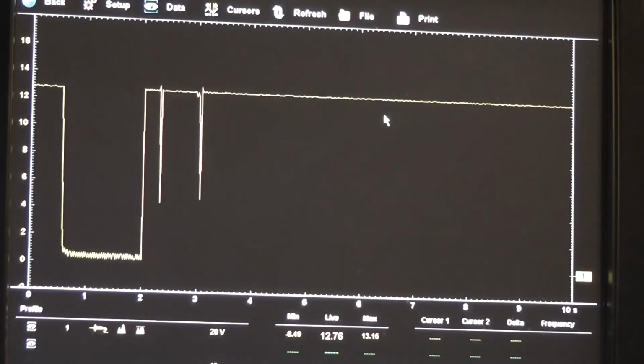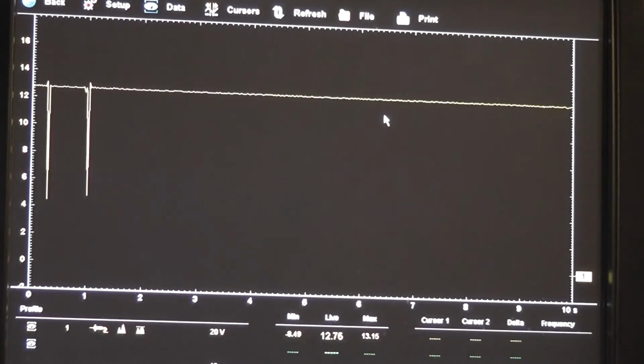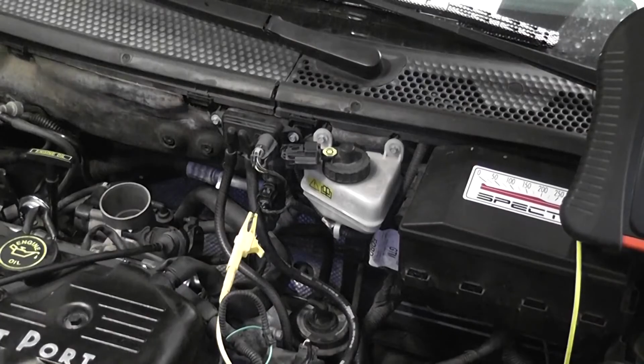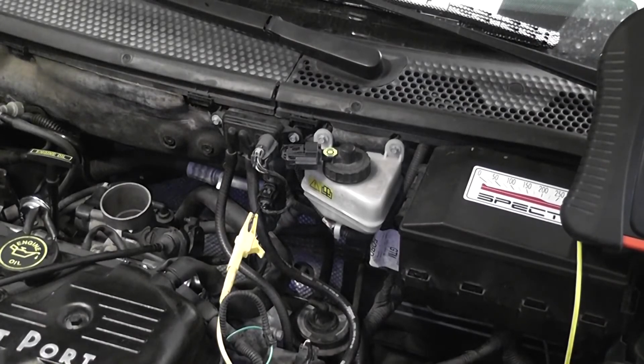And so what that tells you is that power is going into the winding, wrapping through, coming back out, looking for a ground. So that's a fix as far as the solenoid goes. 2 different ways we can go about this from here. We can energize the solenoid manually, force the valve to open. We can show you that one. And then we can also bidirectionally control it, and I like that method too. Okay, I'll show you the test light method first.